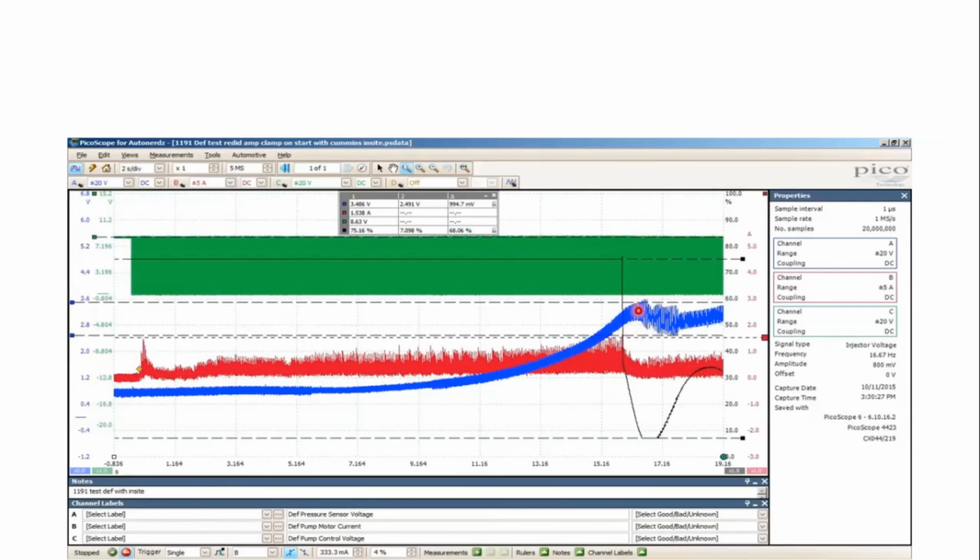But we've got this hash, okay? During normal system operation on a good capture, it'll do this same thing. It will build up the pressure, and then the duty cycle will drop off, and then the pressure will just level off, but it won't have the hash on a good one, and the current will go down. Well, here's my logic behind that and what is happening.